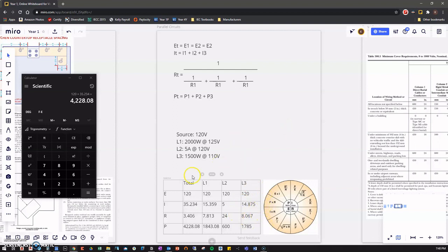But again, the procedure is, on a parallel circuit, fill in your voltage total. That can carry through to all these voltage boxes as well. Now we're going to find fixed resistance using Ohm's law of our given values up here. Plug those in for each load. You could find total resistance. I don't like to do that. Use Ohm's law. Find the other values here, right? Now we can use this rule, I total equals I1 plus I2 plus I3, to give us total amperage. We could do the same exact thing for our power row down here. So there's your parallel circuit rules. Remember, use these 4 rules, use your Ohm's law, find that fixed resistance right off the bat.